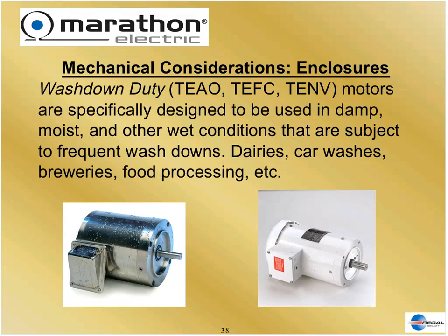Sometimes we have a situation where the motor is in an environment that we need to wash down, especially in a food processing plant or a dairy or even in a car wash. We make motors like that called washdown duty motors. They are totally enclosed. They're also sealed up. All the openings on the shaft, the fan, are sealed with seals. The gaskets seal the conduit box, which is the connecting device from the rest of the motor.